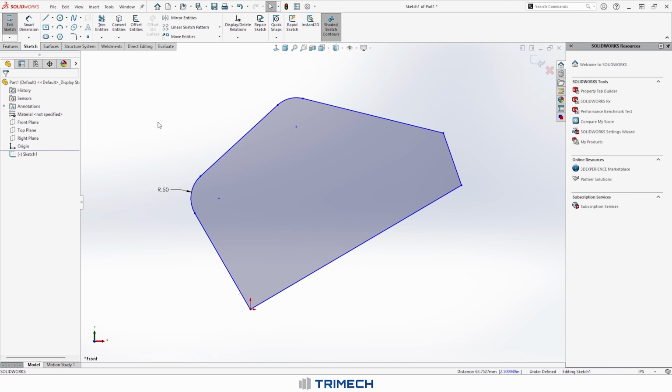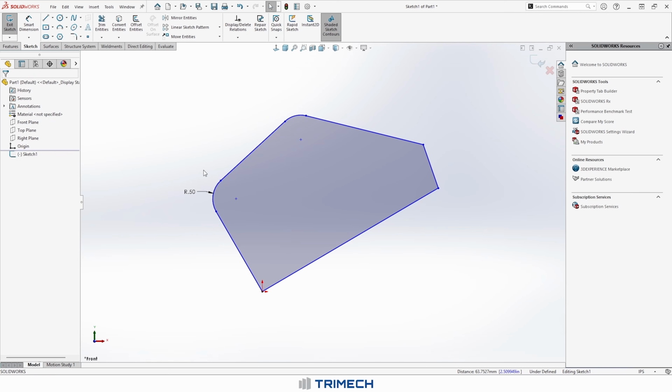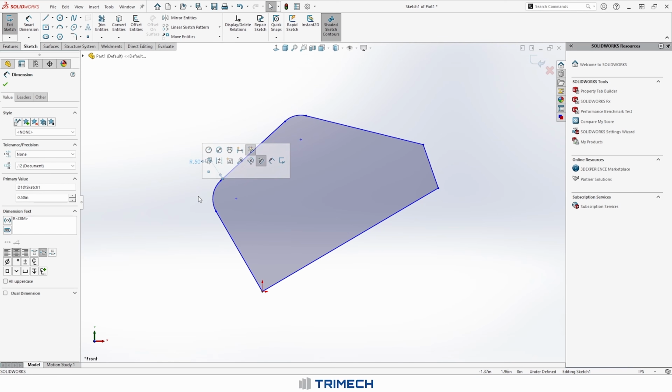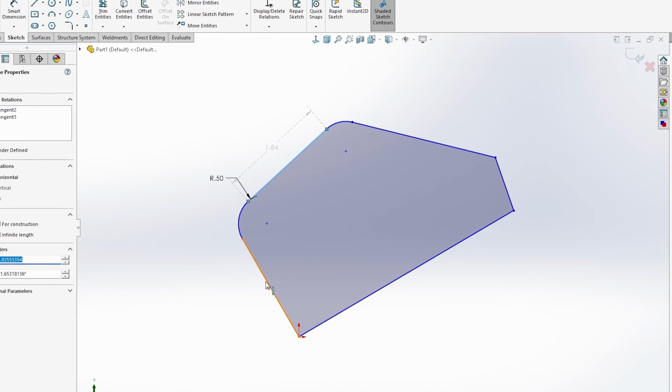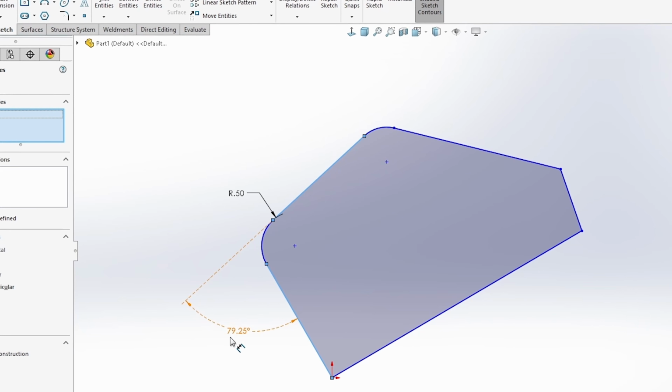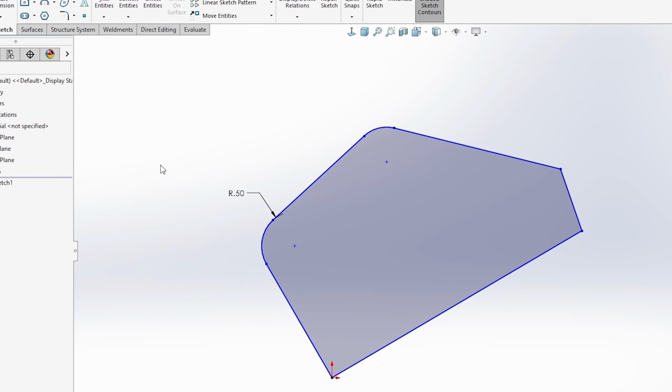So at this point, we've got some features where if we need to know where the corner for either of these radius points is, we're going to have some potential difficulty, particularly because, as I mentioned, these two lines are not perpendicular currently. We're about 80 degrees. So what we want to do is utilize virtual sharps. There are two ways to approach it.